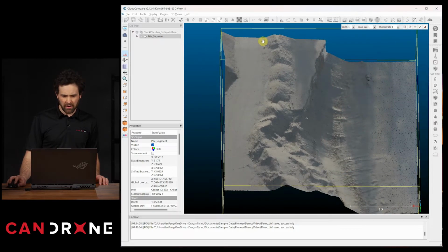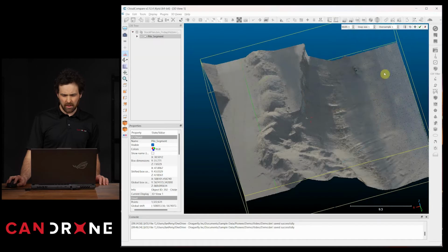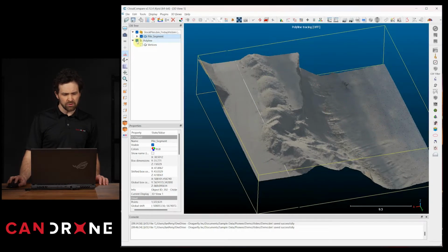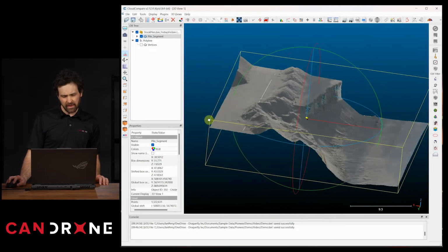So I'm going to go back onto the cloud. Let's say I pause by right clicking, pivot around, click this plus sign to continue on your way. But in this case, I'm just pulling a straight line right across the top, right clicking. Yep, got what I need. I'm going to click this check mark. Now what you see here is it's created a polyline layer in the tree at left.